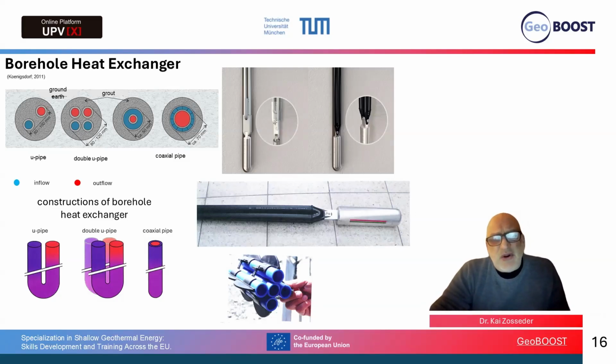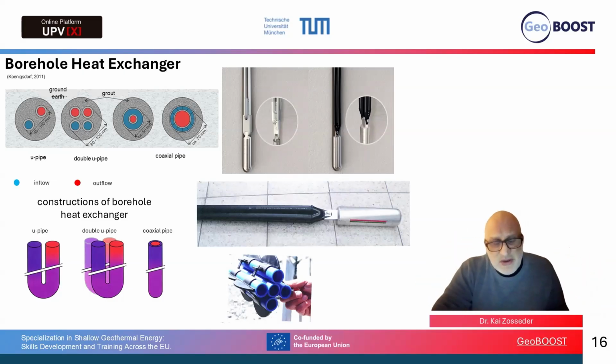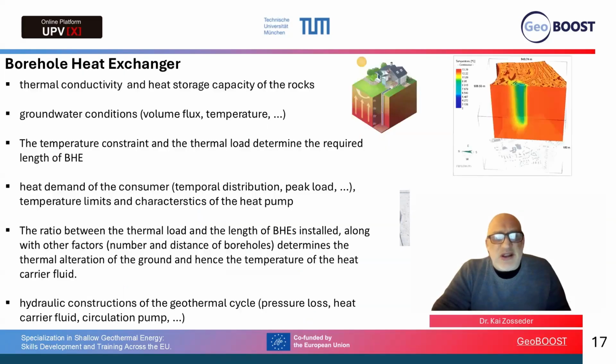And then you see here how such a borehole heat exchanger pipe looks. And here you see also some construction. Here we have also a centralizer, so that these pipes are centrally installed in the borehole. And here in the middle, you have a pipe where you can cement the borehole back. So you see here the backfilling of the borehole is the grout, a cementation, which has also a very good thermal conductivity. So this is how it looks.